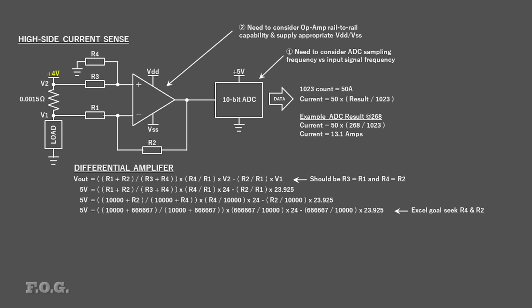First, we can drop the supply voltage down to 4 volts. And yep, it still gives us the 5 volt result we would expect, even at this lower supply voltage. What about if we reduce the current to 2/3 of full scale, which would be 50 millivolts drop instead of the 75? And as we would hope, this gives us 2/3 of 5 volts, which is 3.33 volts. So we can say that the differential amplifier calculation is working as we would expect, so that's all good. Okay, let me put that back to full scale again for a second.